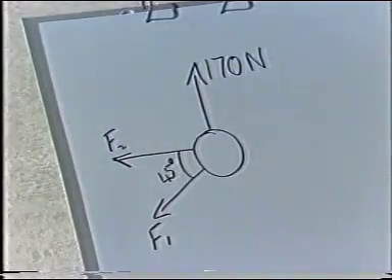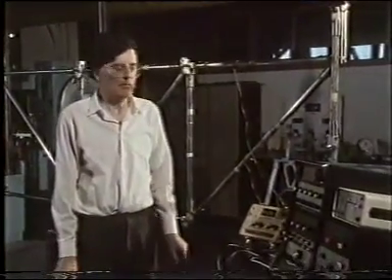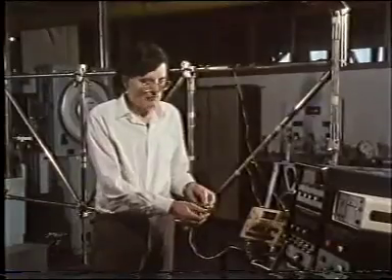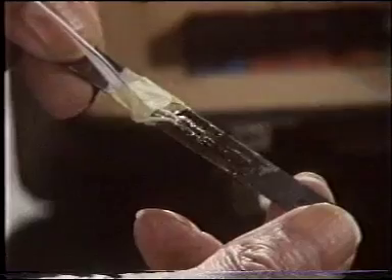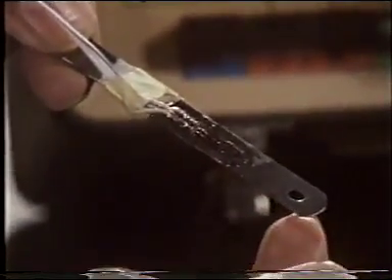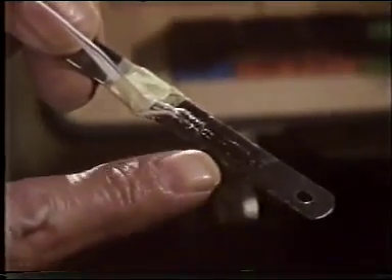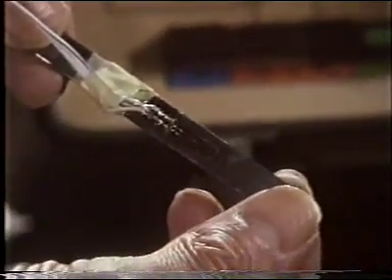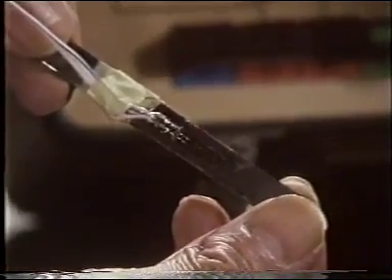Here's Roger again. I'm going to measure the forces in the members using strain gauges. A strain gauge is a small patch stuck onto the surface of a member, just like this one here. It consists of very fine wire closely bonded to the surface of the metal. And I've got here a piece of metal with a strain gauge stuck onto it. The idea is that if you apply a load, the member extends, and because the strain gauge is closely bonded, it extends as well, thus altering the electrical resistance.